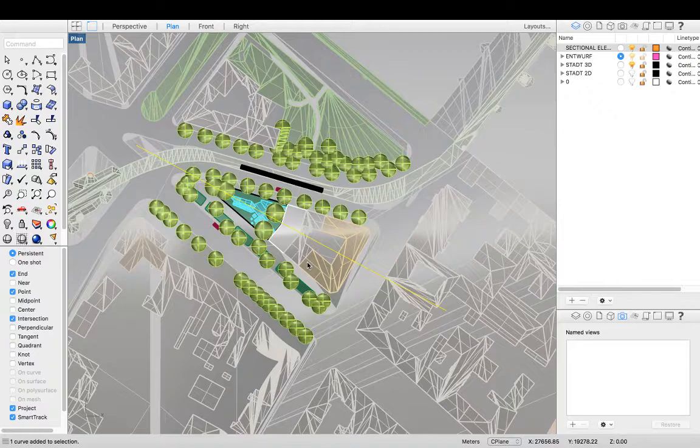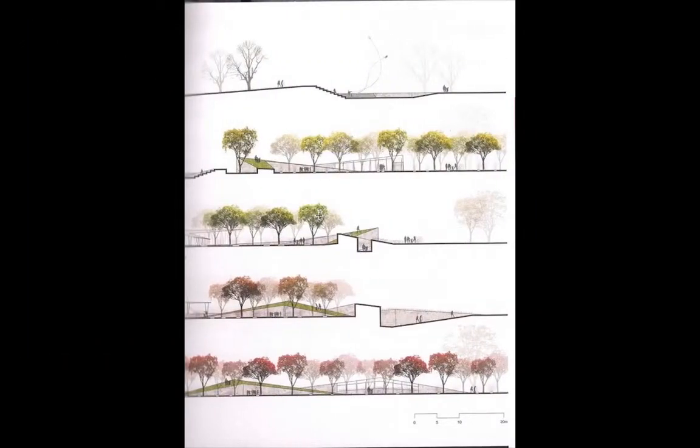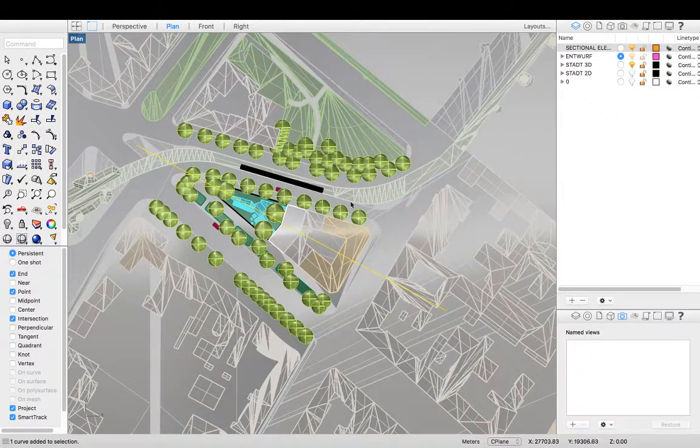Now, with the section elevation, the principle is that you have a section line which is your cut line, which is usually thicker, and then it shows detail behind that line, which is usually fainter in the background, and so you get more information. For example, here this is mostly just a section line with background elements displayed softly with a lighter line quality, as you can see. This is a very simple example of a sectional elevation. We're going to do roughly the same.